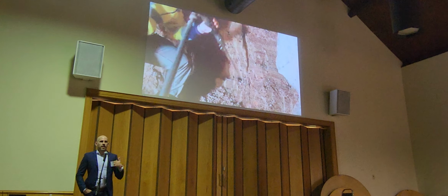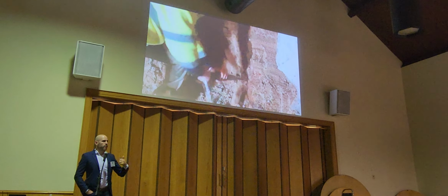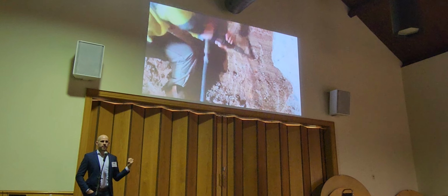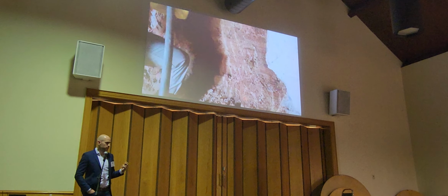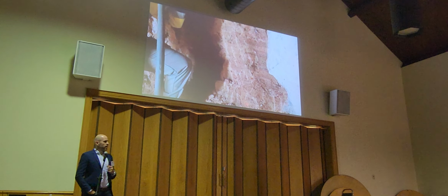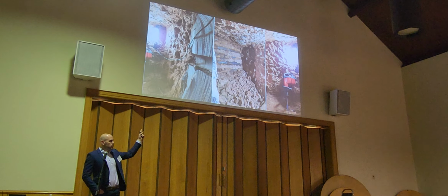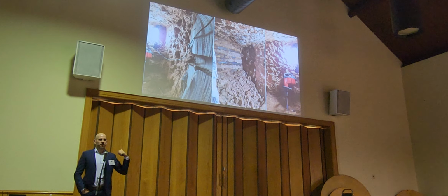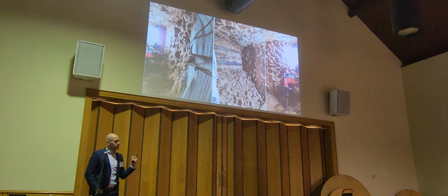And then they understood also, okay, if I'm talking about gel and I had a very, very porous soil with no fine content, very, very low angle of friction, so even no stability, and now I have something which is reliable, which is standing by itself, and where I can work in. Please don't get me wrong, but I didn't recommend to take this as a final support. But you see what this material, a jelly product, can do in the soil.